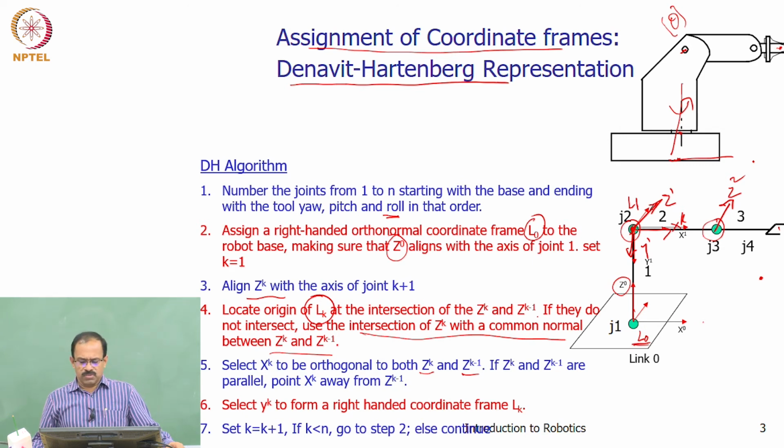See, when they say it's outside, basically I am telling it is 180 degrees apart. My z axis is rotated by 180 degrees. I can take this direction or this direction. It is optional, but normally we try to reduce the rotation in the frame, but you can still have it as this direction, or you can even assume this direction. Nothing wrong in assuming this direction. So here I am telling there is no rotation. If it is this direction, there is a 180 degree rotation between the two z axes, z1 and z2, 180 degrees apart.